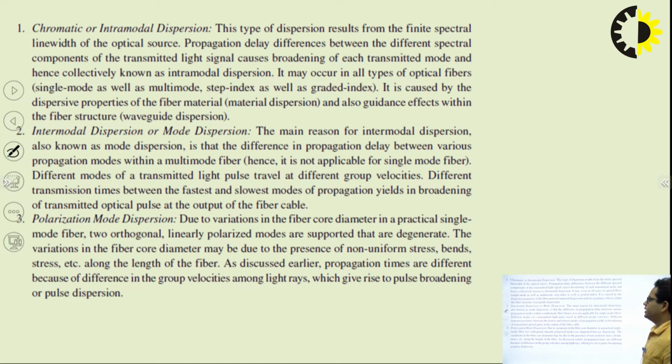The next thing is the intermodal dispersion. What is this intermodal dispersion? The main point responsible for intermodal dispersion is the difference in the propagation delay between the various modes propagating through the fiber. And remember this: if we are talking about intermodal dispersion, it will definitely occur inside the multimode fiber.